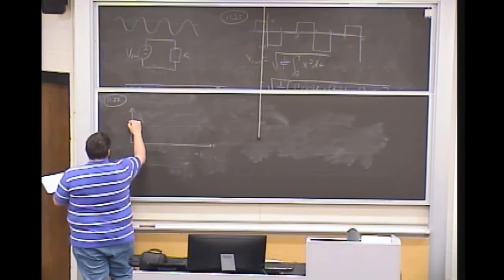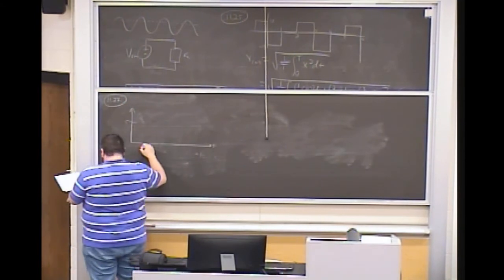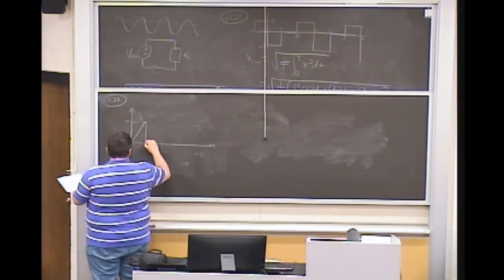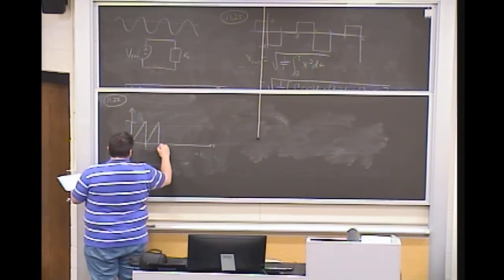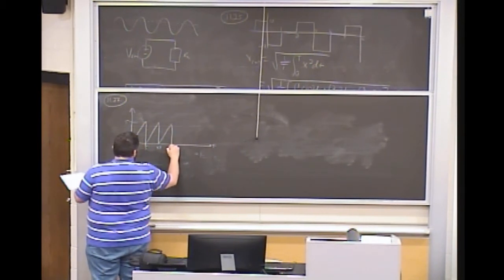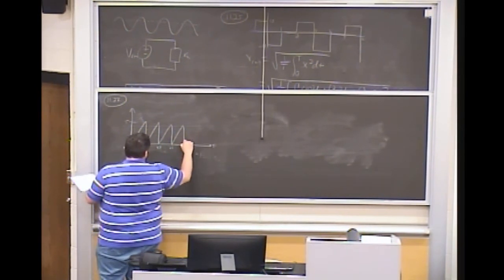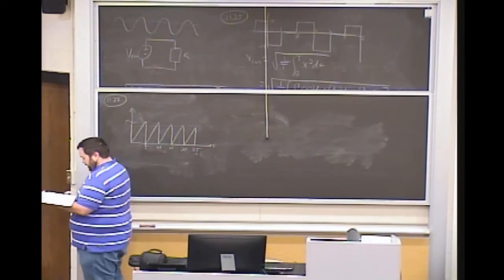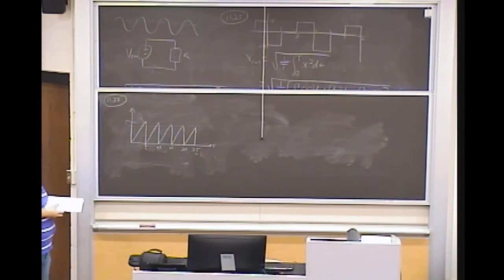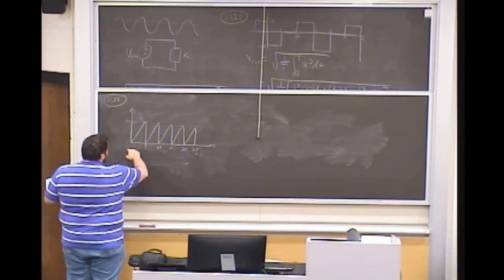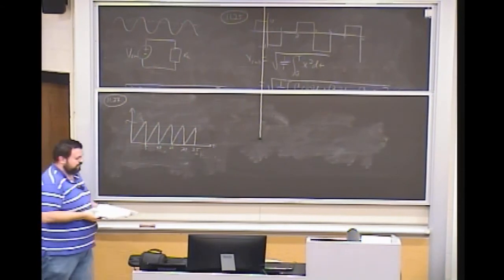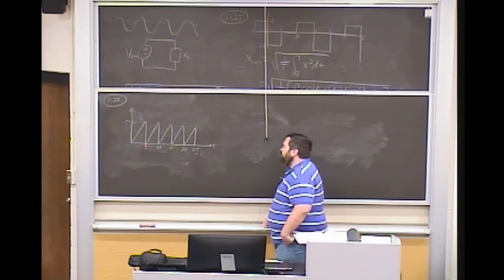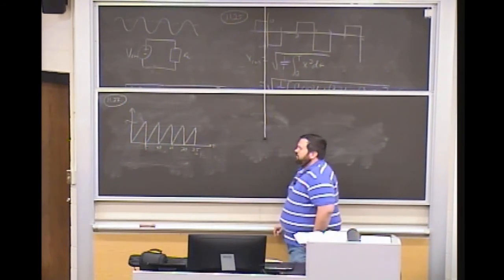And so here it peaks at 5, and you're given here's a 5. So every 5 seconds, presumably, you end up having this kind of right triangle looking pattern. And so you're asked to find IRMS. This is a current. So how do we go about doing that?